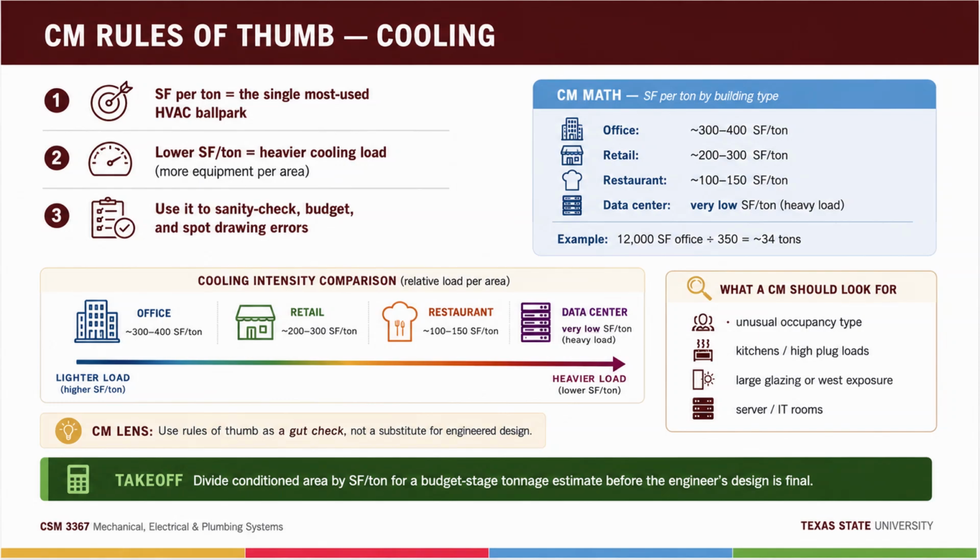And here's the good news story of the last 2 decades. The old fluorescent era ran 2-3 watts a foot. The LED revolution didn't just cut lighting bills, it cut cooling loads in every building it touched, which is why lighting retrofits sometimes let you downsize replacement HVAC equipment. 2 line items on your estimate, connected by 3.412.